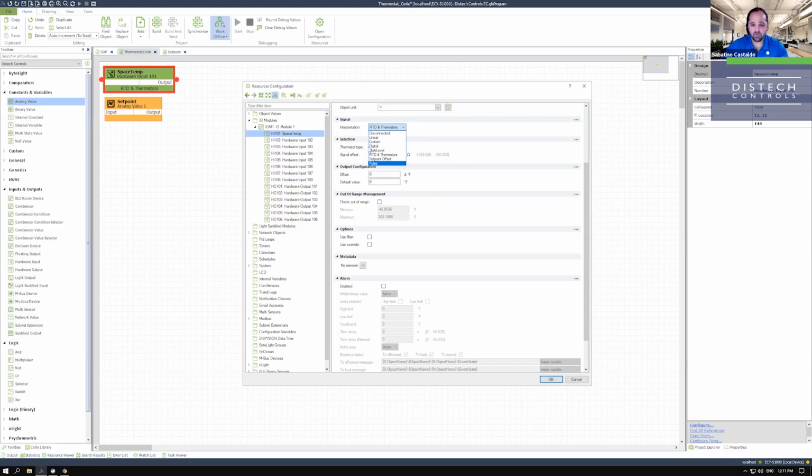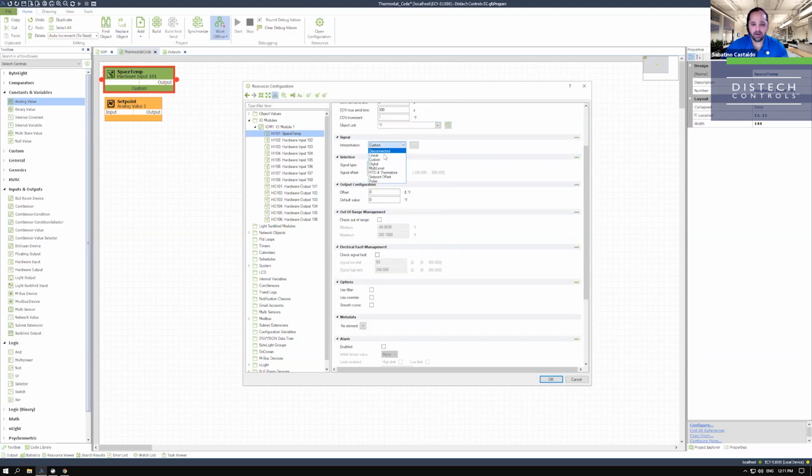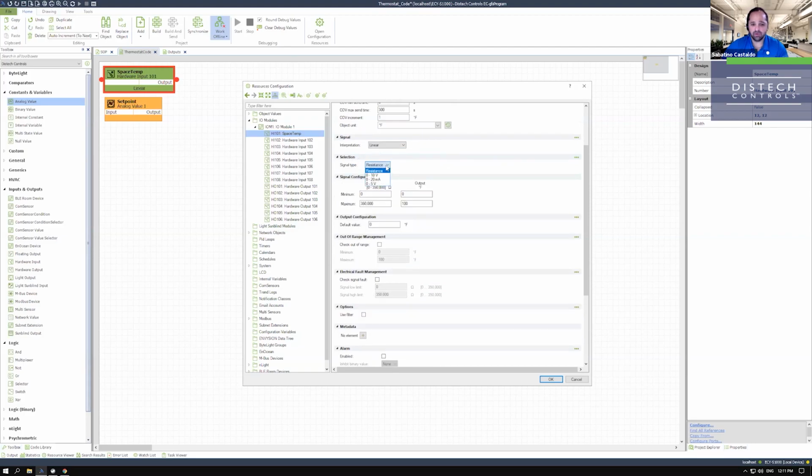And the options will change as you select them. So say, for example, I were to select linear. Okay, we'll have resistance, 0 to 10, 0 to 20, 0 to 5. Can I do 4 to 20? Absolutely. Pick 0 to 20, make this a 4, and you're at 4 to 20 at this point, right? We'll just ignore what happens from 0 to 4. We're never going to get 0 to 4 because your sensor will only give us 4 milliamps anyway.